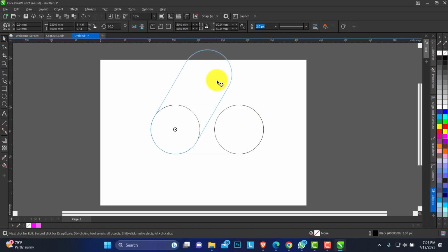Okay, so you will rotate to the angle of 60 degrees. Right click, holding your left mouse button, and that will duplicate it. So we do the same thing for this other part again. Click on the circle, change the point, this time from this angle, 60 degrees.